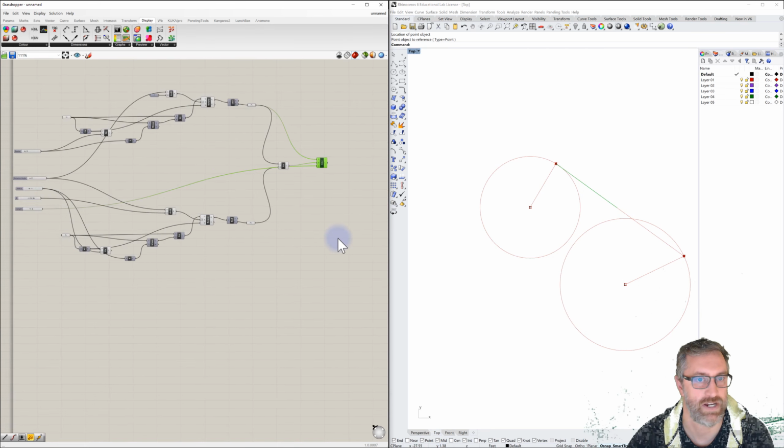Okay, and what I'm trying to do is make sure that the length of that new line is longer so that it doesn't slide off from itself. It'll work fine, but it just looks weird when that does that. Okay, so that's working. I'm just going to rename these so that we know what they are. I'm going to call this outrigger length.